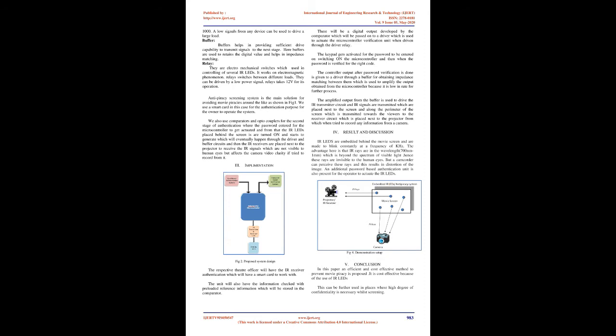These are connected to the microcontroller using input/output pins. Optocouplers. Optocouplers transfer electrical signals to provide coupling with electrical isolation between their input and output. Transmission takes place using light waves. Optocouplers prevent rapid changes in voltage on one side of a circuit from distorting transmissions or damaging components on the other side of the circuit, thus ensuring isolation. An optocoupler consists of a photodiode and a phototransistor.